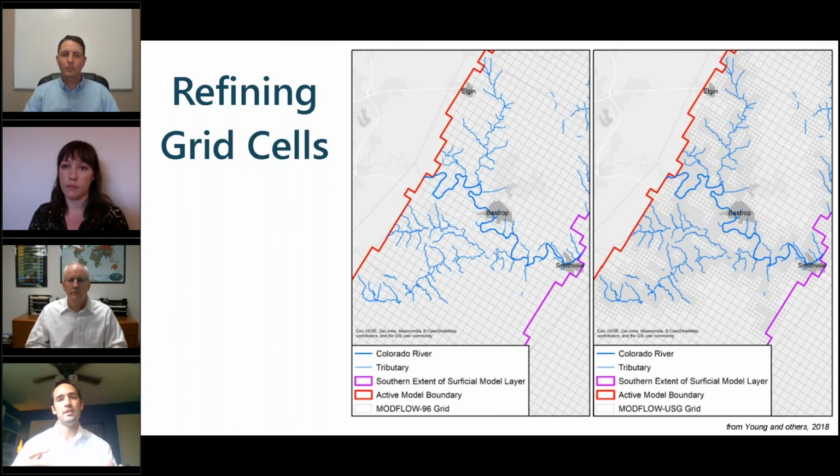I mean, yes, you have the highest active cell available in that option, say the recharge package, and then you can do cell re-wetting and it mitigates that somewhat, but then you get too many cells drying or re-wetting, and you get convergence issues. So of course, all this ties together a little bit.